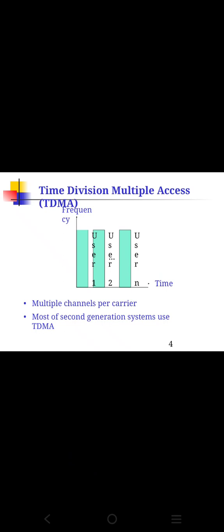The handoff process is simpler here. TDMA uses different time slots for transmission and reception, so duplexers are not required. The main advantage of TDMA is that it is possible to allocate a different number of time slots per frame to different users. Bandwidth can be supplied on demand to different users by reassigning time slots based on their priority.